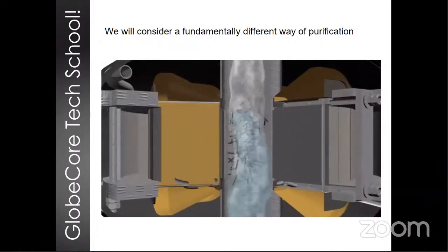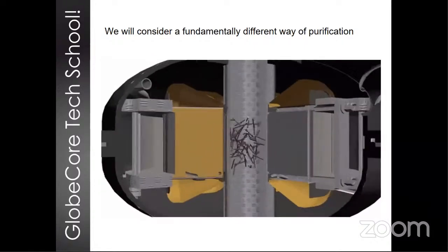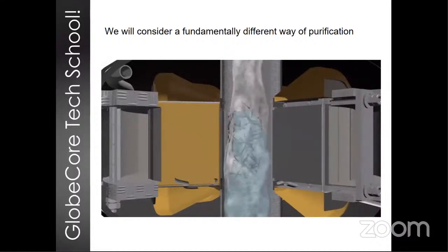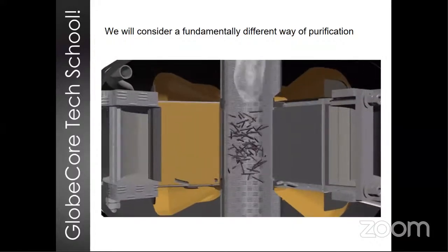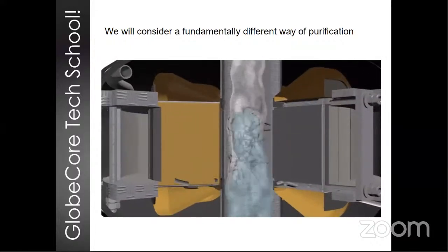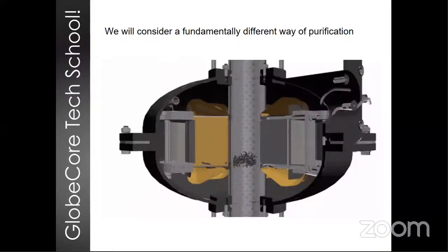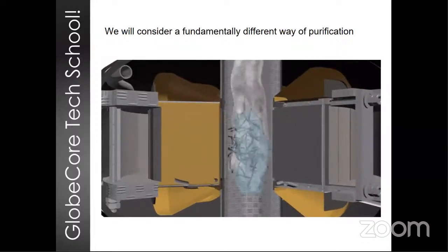The tube, the process chamber, contains metallic ferromagnetic particles. And so when we power up the inductor, this rotating electromagnetic field in the chamber acts on these ferromagnetic particles, and they begin moving along very complex and chaotic trajectories. They collide with each other and go every which way. They collide with the walls of the chamber.